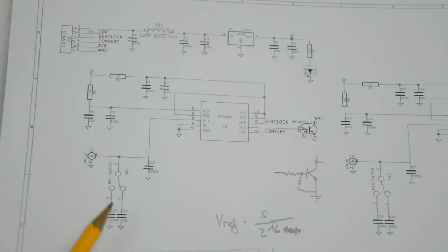First of all, there is a switch here with two capacitors. And what these capacitors do is, this is actually the video bandwidth of the spectrum analyzer. The log detector that is connected to this SMA connector here has an output impedance of about 3K or so.